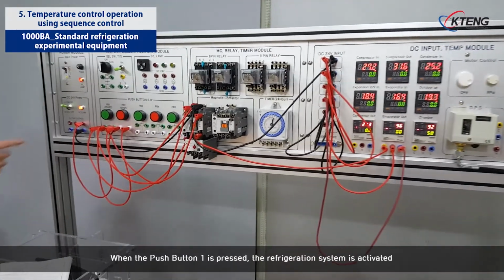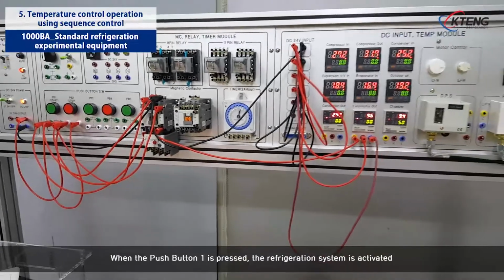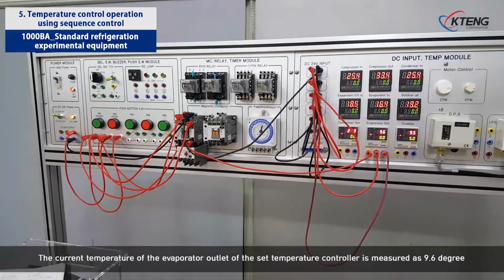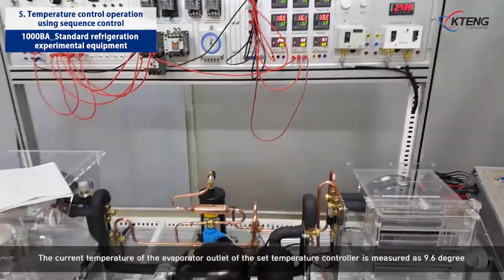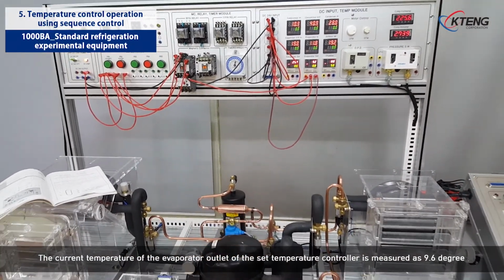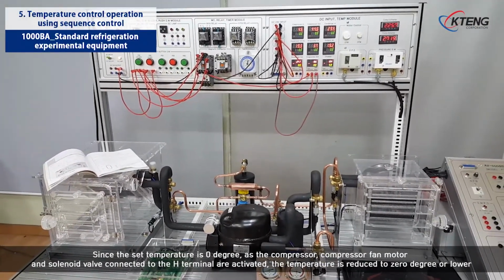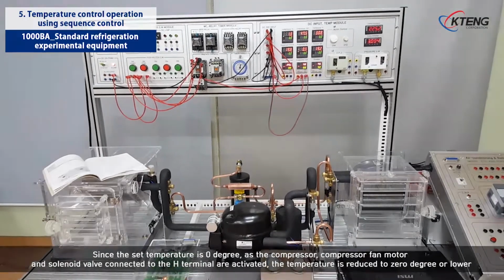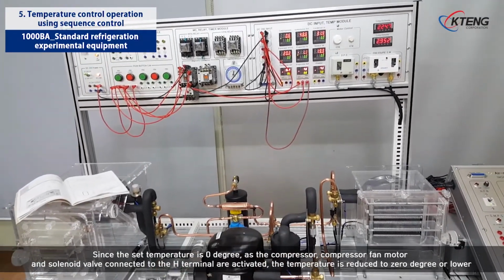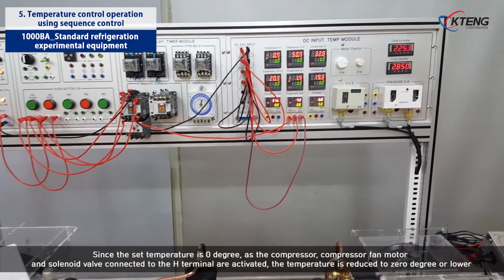When the push button 1 is pressed, the refrigeration system is activated. The current temperature of the evaporator outlet of the set temperature controller is measured as 9.6 degrees. Since the set temperature is 0 degrees, as the compressor, fan motor, and solenoid valve connected to the H terminal are activated, the temperature is reduced to 0 degree or lower.